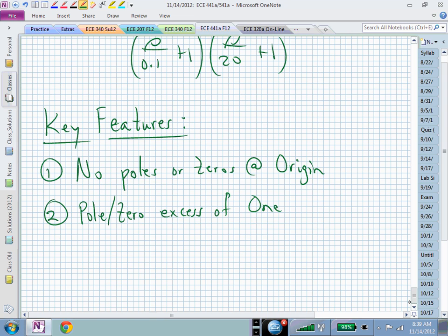And what does that tell us relative to the behavior of that transfer function as our frequency gets large? Now we know what the magnitude will do. Our transfer function at high frequencies is looking like a 1 over s, and that's going to slope consistent with a single pole.